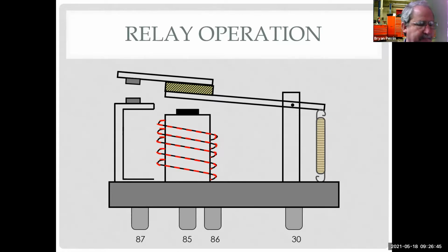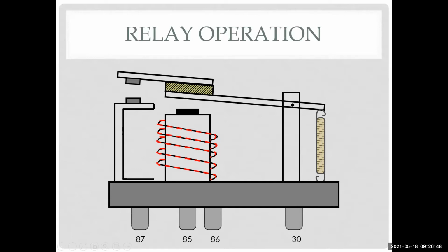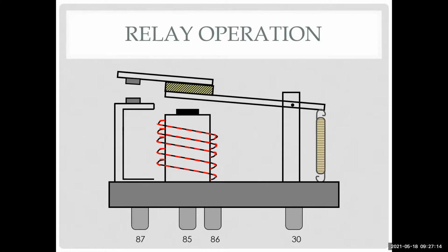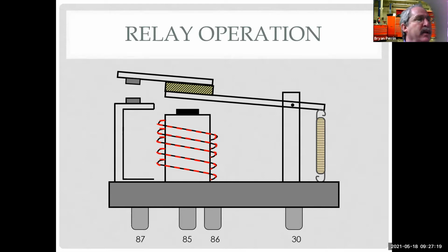Okay. All right. And is there a typical convention, like in the example you just gave, 86 being the power coming from the headlight high beam switch, 85 being the ground? Is that normally the case? 85 is the ground, or does it go back and forth? Yeah, that's all DIN wiring, and unless I made a mistake, my memory is 86 is power and 85 is ground. Okay, just curious. And some of them, it doesn't make a difference. You can run them either way. Other ones have a diode and they'll only work one way. But my memory on the DIN numbering is 86 is the power side and 85 is the ground side.